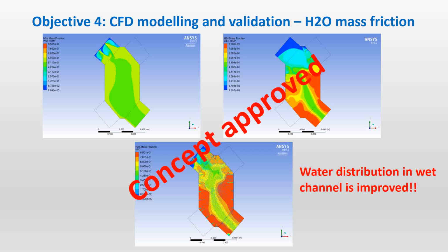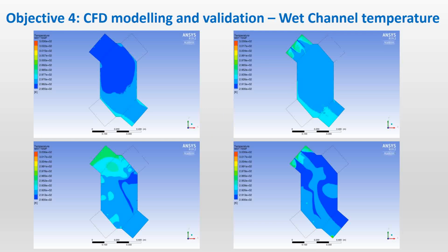So that's what's happening in terms of the temperature in the wet channel. This is the HRV. We just put 296 Kelvin, no water spraying. This will be the temperature distribution. Turn on the external sprayer. This can take the temperature down to about the blue one, 292. The internal sprayer can take it further in some regions to 291. All sprayer mode can take the temperature outside to 290 because the water evaporation starts to appear. And this goes down further.